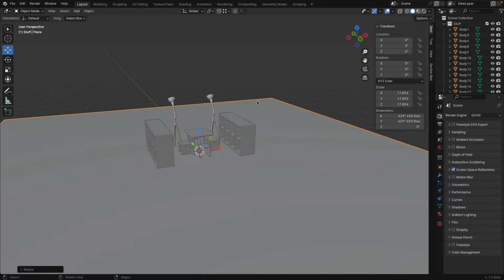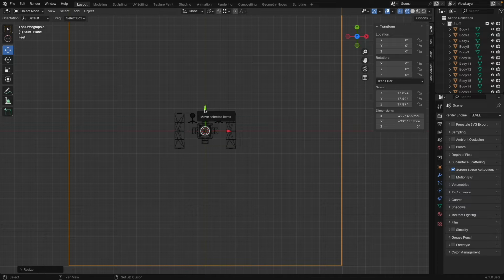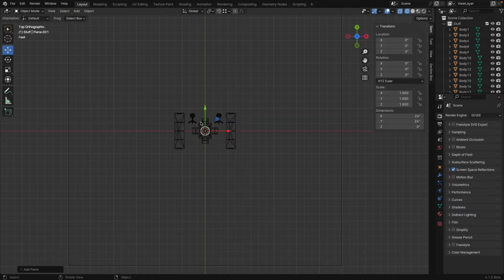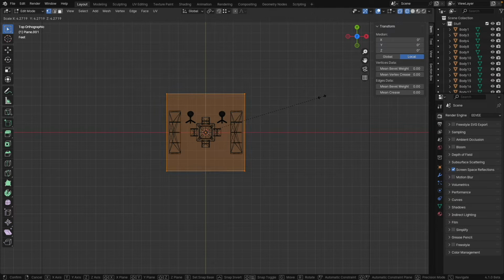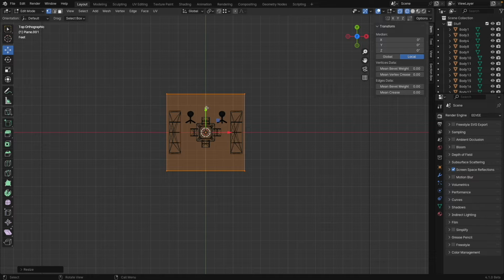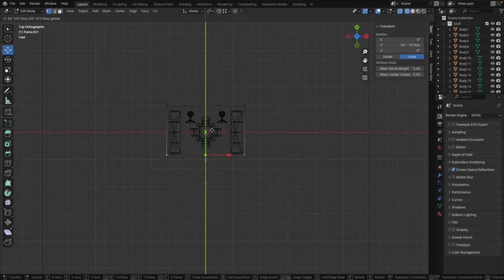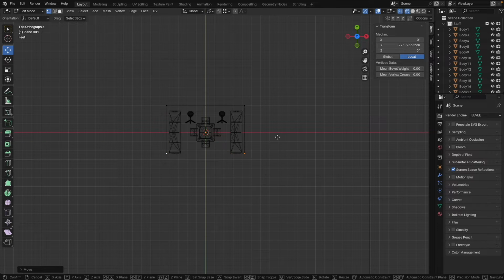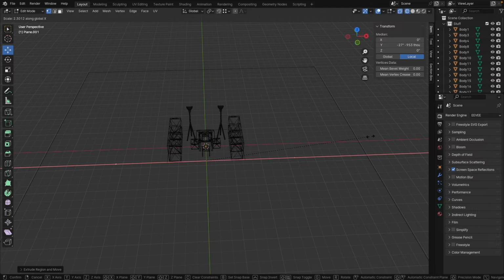Then, because the world here is kind of open, we need to have some walls. Let's make an environment. Z and wireframe. Shift A and add a plane. Going to edit mode. Then we press S to scale this up a little bit, maybe like this. Bring this down with Shift left mouse button. Click these 2 points, X, and select the edges. Select those, move them up maybe to here, and then I press E and escape, and then S and X, and you see I scale them away.